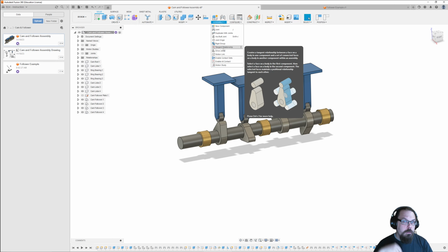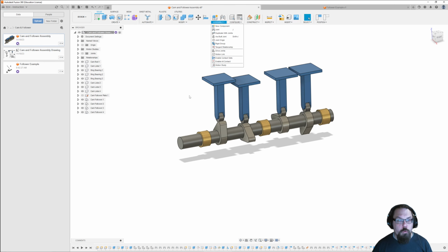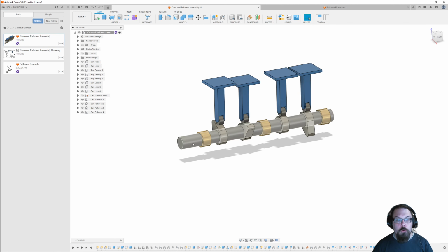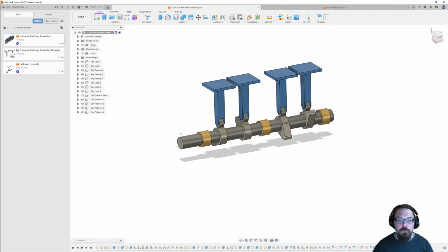This is actually much closer to a geometric constraint in its behavior in the sketch menu than it is an actual joint. But for the tangent relationship to work properly in this circumstance, we have to work with joints in a way where we relate them to each other, or use them in a coordinated fashion to control the axes of movement that are allowed in the machine to accurately create this motion simulation that we're seeing.